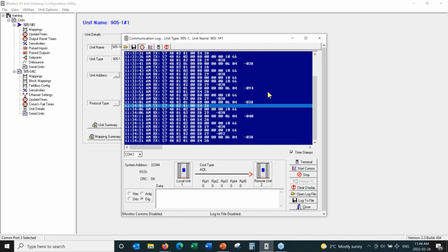So let's say we had a couple of trees in the path, and the radios were, say, 1 mile apart. And let's say we had 3 or 4 trees blocking line of sight, then we would expect to see an RSSI of, say, between -70 and -80. So it'll bounce around a fair bit, but we could say the RSSI, averaging things out, would probably be around -75.